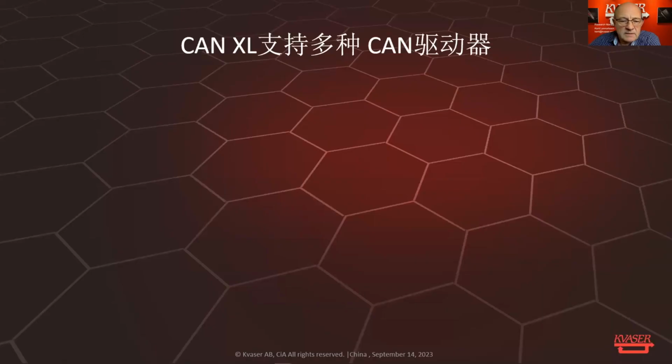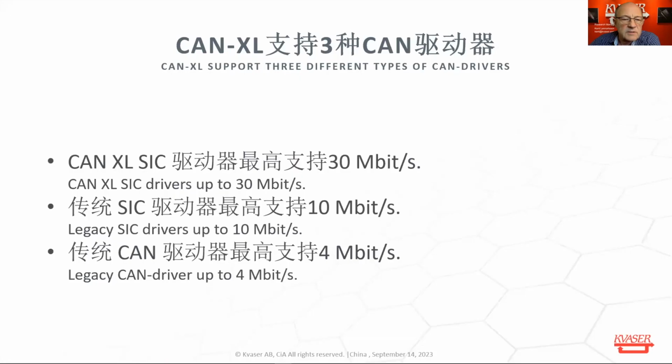So in the next section, we'll talk a little bit more about the new CAN drivers. The new CAN driver is called CAN XL SIC, Signal Improved CAN driver. And due to this mode switch, where you go from dominant and recessive bits into push-pull bits in the data rate, you can probably get to 30 megabit per second in a good network.